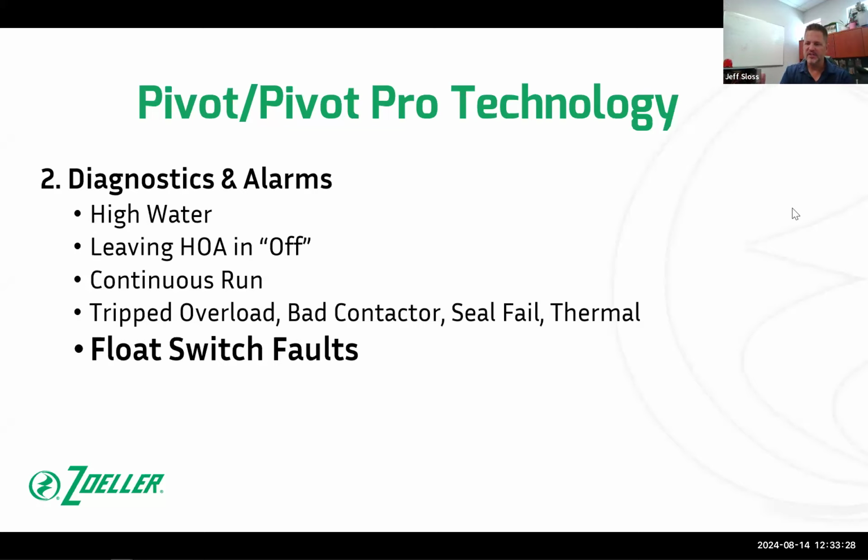And yeah, you touched on something. Sometimes the stop float gets stuck, but sometimes other floats get stuck. So let's say stop and lead, or just lead got stuck. The panel's able to kind of sort that all out and make decisions based on what it does know. And every once in a while, a wise guy says, well, what if none of the floats are working? I can't help you there. There's nothing we can do about that. But we can work with what inputs we do get and try to make the best decision possible to keep the property from sustaining any damage. And that's the whole goal.